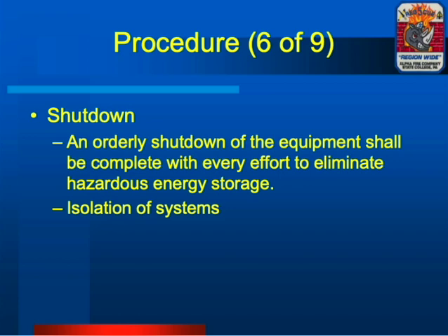The authorized member then shall bring all necessary energy sources, as determined, to zero energy, as I just stated. And this will apply to any electrical, mechanical, pneumatic, hydraulic, or thermal energy sources which may create a hazardous condition during the completion of the required operation. These energy sources must be either physically disconnected from the machine or an energy isolation device shall be installed and utilized. So then we're going to talk about disconnecting physically versus using a breaker or a switch.